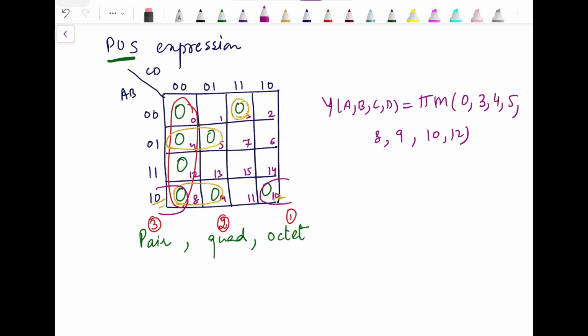So now we can say that this max term is used in three different combinations. But why have we used this in three different combinations? Because we were having individual zeros. Firstly, we have used it in the quad, then we have one individual zero lying over here, so there is a possibility to make the pair instead of keeping it single. Then the same is over here.